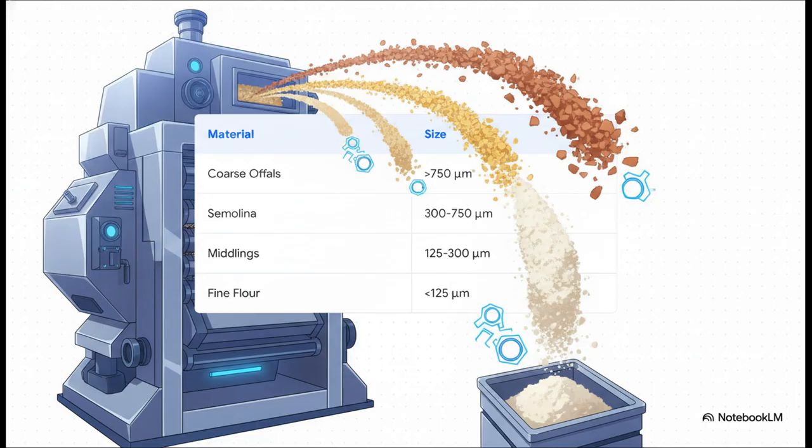This strict precision grading dictates your entire loading strategy for the upcoming reduction stage. Semolina, due to its larger mass, requires a significantly different roll gap and reduction setting than smaller Middlings to ensure uniform particle size distribution.